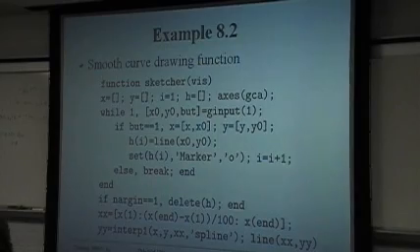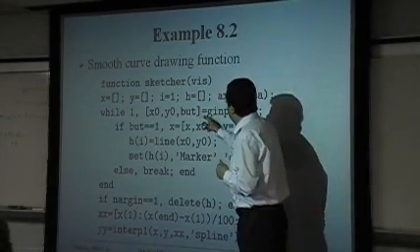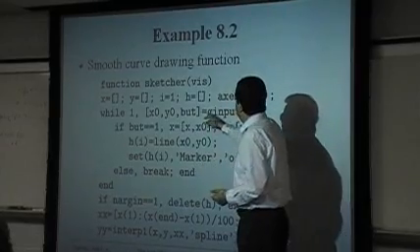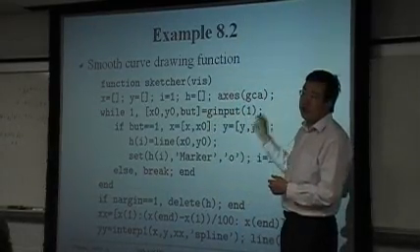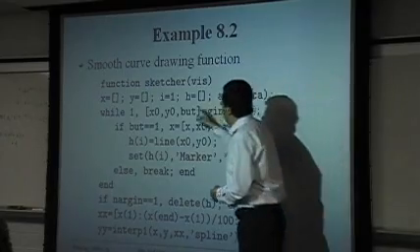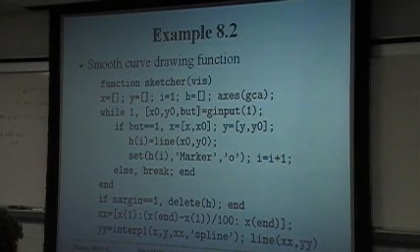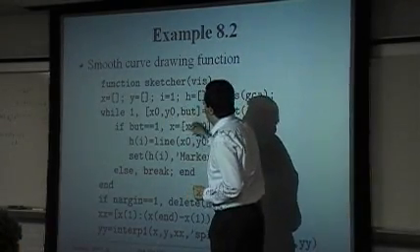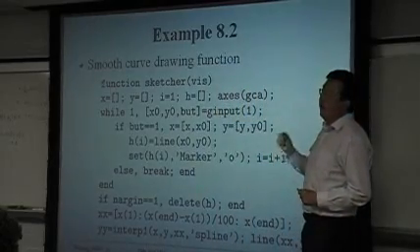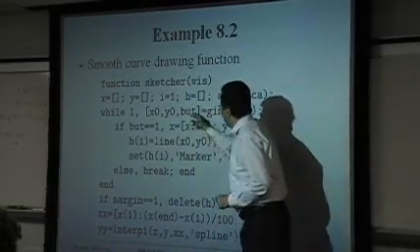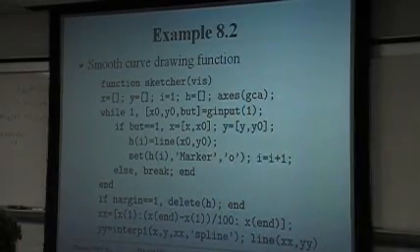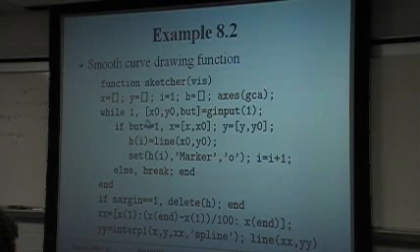Actually, I will say something about the ginput function, which is used to read the data. In this case, 1 here means I can use the mouse to click on the graph and pick one data point, where x0 and y0 are returned, and this one is the button value: 1 for left button, 2 for middle, and 3 for right button. And you can use this to select data on the graph or at coordinates.